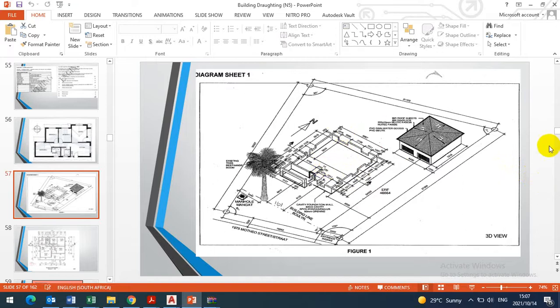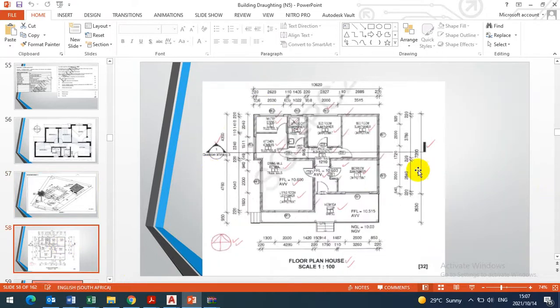That's when you make a copy to use for the floor plan, because the two drawings are on a different scale. Site plan is on 1 to 200. After you scale down and then you use that to draw a floor plan is wrong. Before you scale down, have a copy on 1 to 1, and then you will use it for the floor plan. When you finish putting everything before dimensioning, before texting, you have to scale down your drawing.